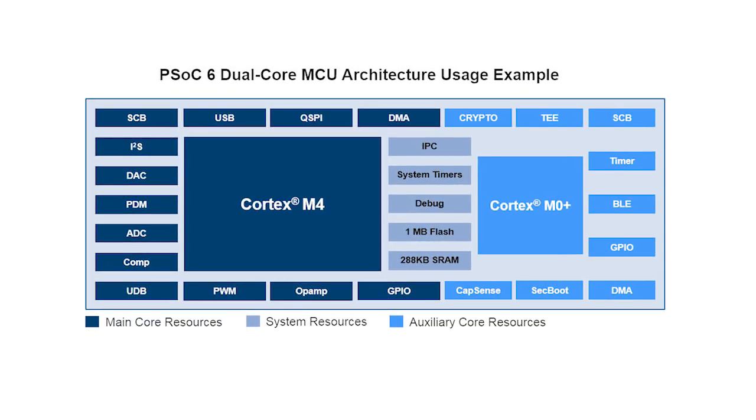Let's pause here for a moment and talk about the system architecture briefly. The PSoC 6 BLE device that we're using for these videos is a dual-core ARM Cortex M4 and an ARM Cortex M0 Plus. This is a shared memory multiprocessor architecture, meaning both of the processors can talk to everything in the chip. That includes the RAM, the flash, and the other peripherals. With the advanced security features of PSoC 6, which I'll talk about in later videos, we provide you the ability to lock down your project in a very flexible, very secure way.